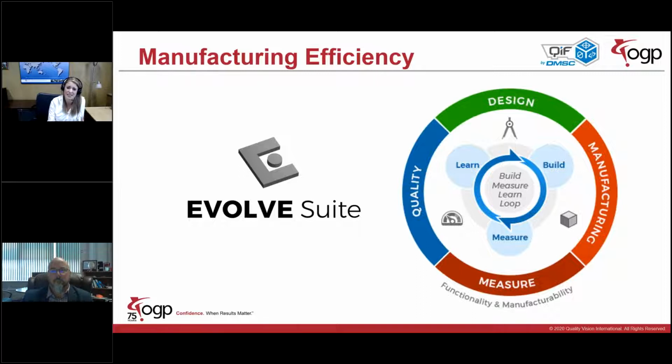But unfortunately, this usually is not the case in today's manufacturing companies. For example, maybe the design engineer does not apply the GD&T properly per the standard, or doesn't add the tolerances to the 3D CAD model in a way that can be used downstream in inspection. On the other side, sometimes production engineers don't know the best way to adjust their machining process when quality gives them their GD&T results. Production engineers want to work in their manufacturing coordinate systems and adjust their fixtures and their tool offsets, as opposed to working with and analyzing a complex GD&T datum structure.